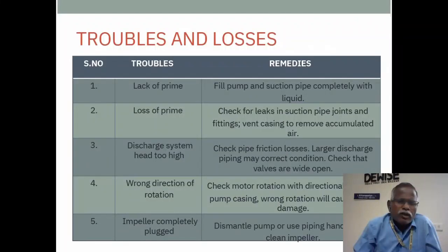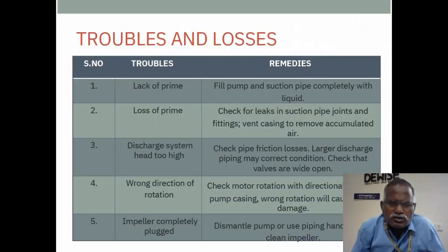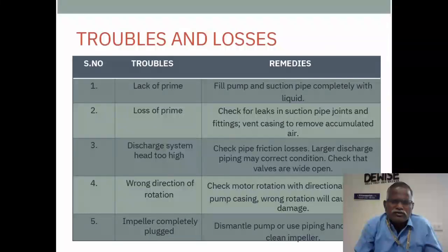Okay, and then the discharge system's head is too high. What's the trouble? Check the pipe friction losses. A larger discharge pipe may correct the conditions. Check that the valves are wide open.